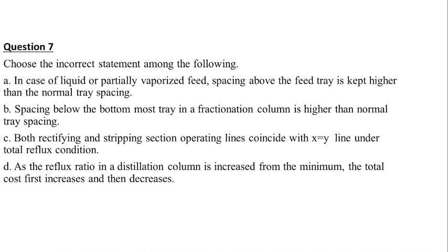Moving to question number 7. Choose the incorrect statement among the following. In case of liquid or partially vaporized feed, spacing above the feed tray is kept higher than normal tray spacing. This statement is true actually, and spacing below the bottommost tray in the fractionating column is higher than normal tray spacing. This is also true.